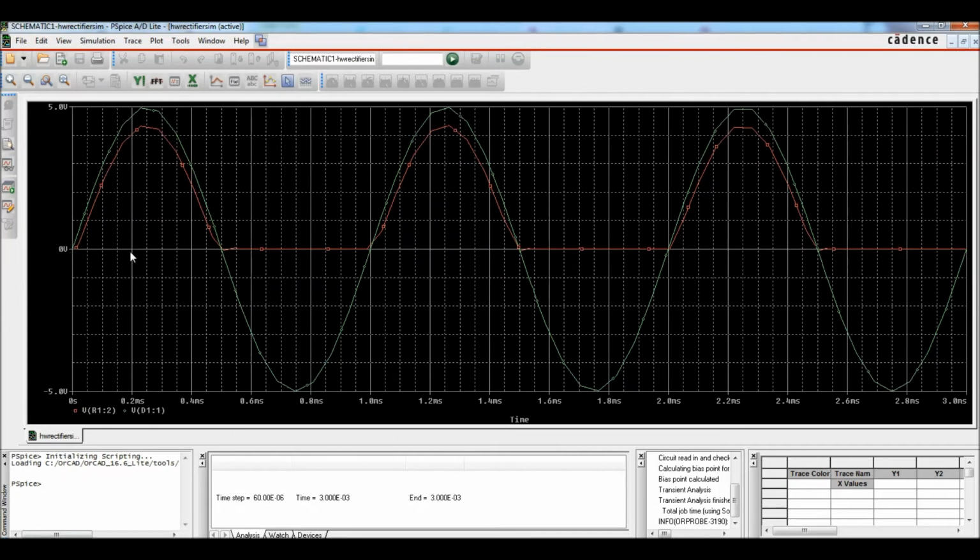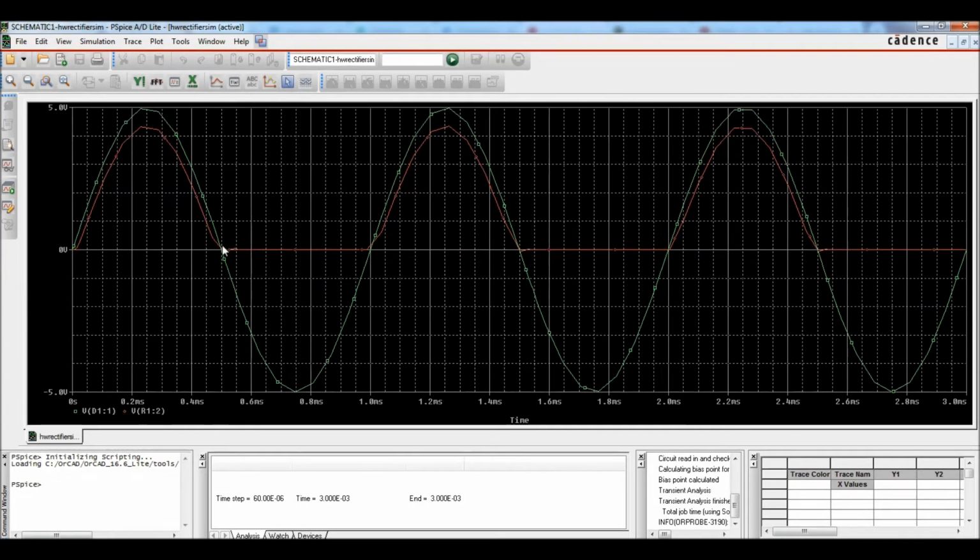This is because the diode has to wait for the input signal to reach V gamma. Only then will it turn on, and then you get the output signal. During the negative cycle, the diode is turned off, so there is no output voltage. V equals IR, and your I is 0, so the output voltage is 0.